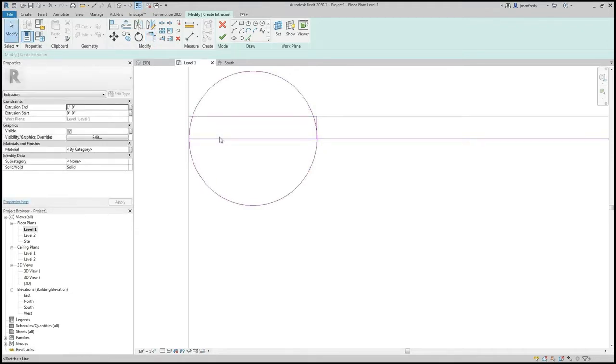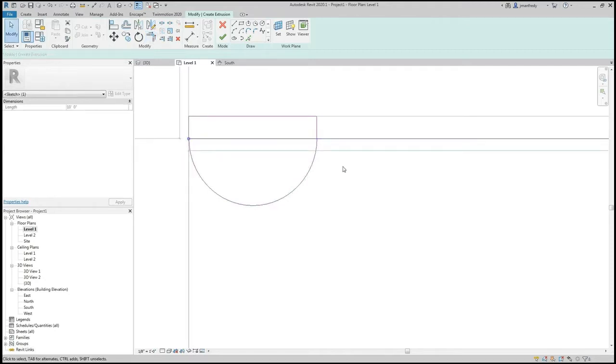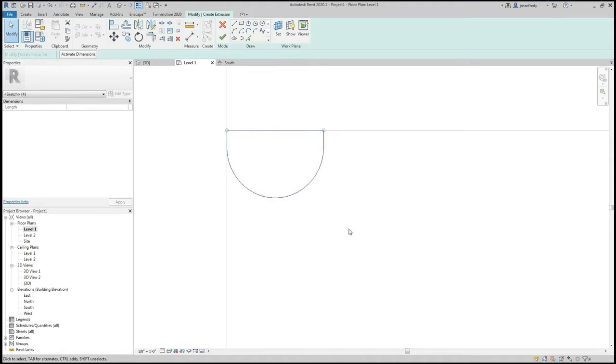I will draw a little line here, and I'm trying to make a profile of that half round with this 1/2 inch piece in the background. So here I'll split the circle, split line command there, split the circle so I can trim this side, or TR here to here to cut off half the circle, and the TR command is right there. And I can click on this and this vertical line here, and then I no longer need this guideline. I hit delete on my keyboard. So I've got that object right there.